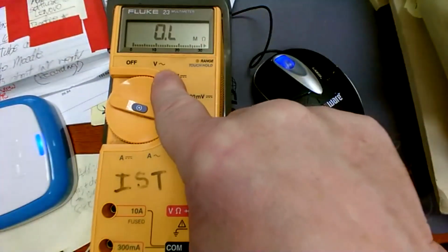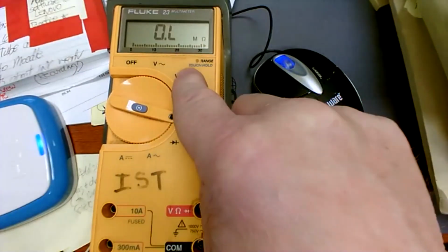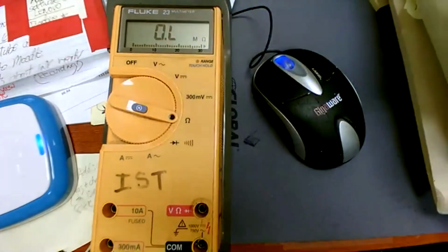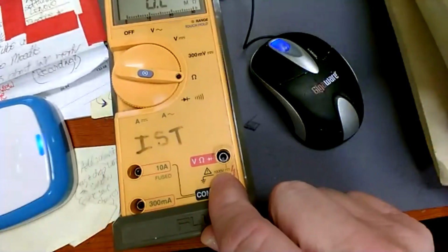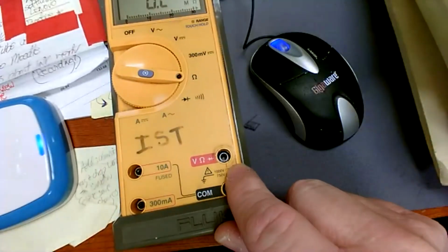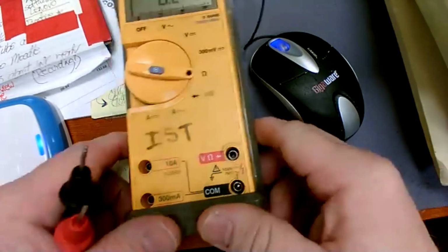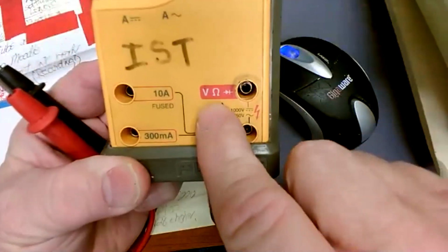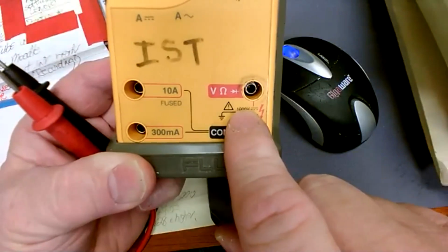If any of you go to buy a meter, always remember that whether you're reading ohms or volts or amps, look at the specifications on the meter and realize what the limits are. Here, the limits for voltage would be 1,000 volts DC or 750 volts AC. Y'all see that? So it's actually telling you on this meter, you can't read any higher than 750 volts AC or 1,000 DC.